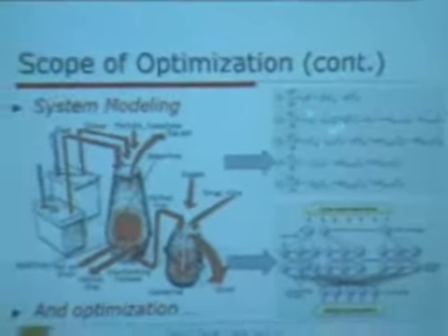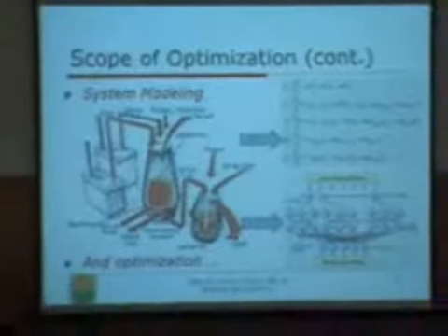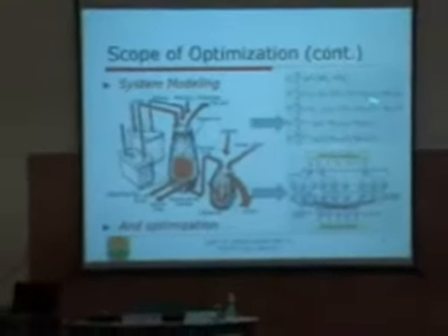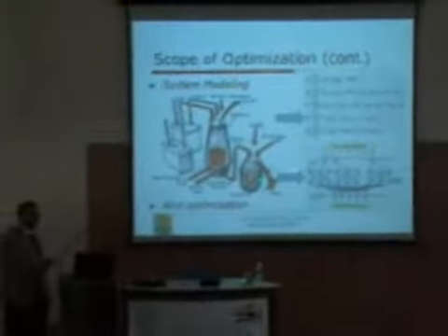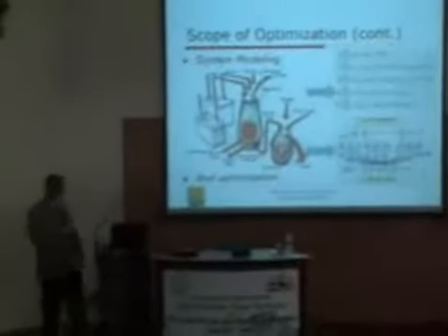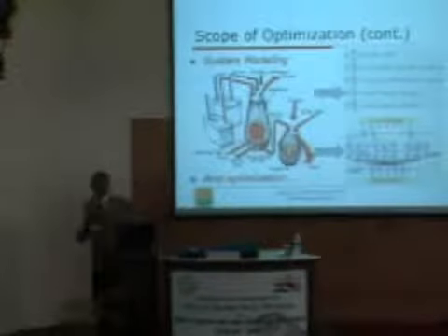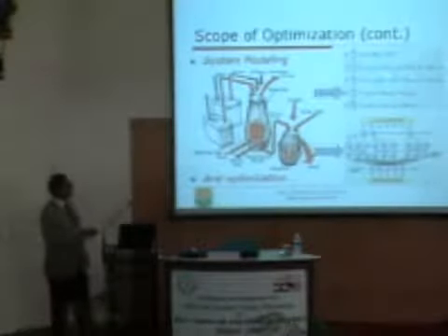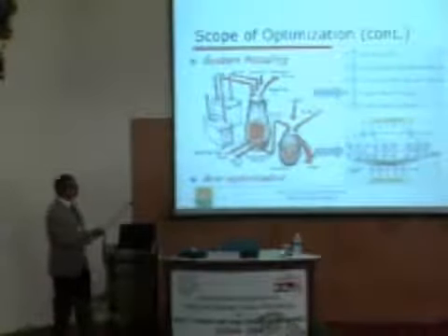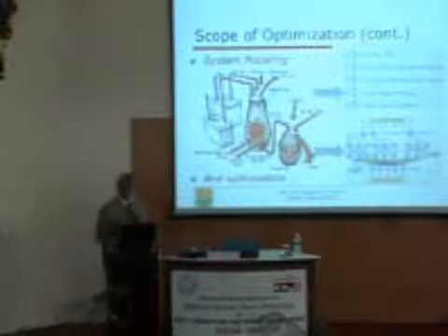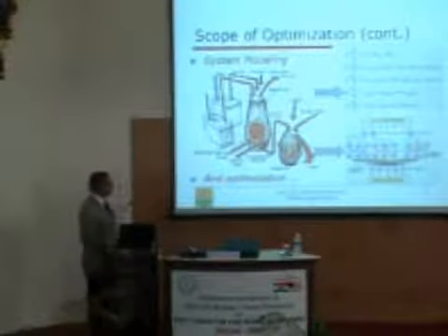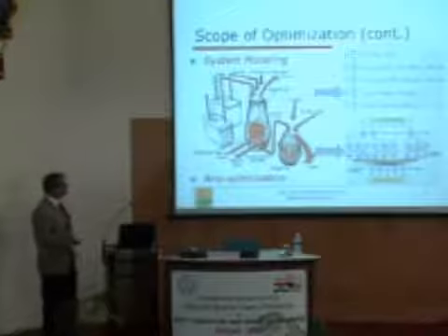So for a particular value of those, I run this model, and I check the output that's coming out of this model against the output of the plant, and then the error that I have, I call that an objective function. So if I run an optimization on top, I may be able to get the parameters which are going to fit my data well with the model. So then you get an idea of the model. So that's one common way people do modeling.